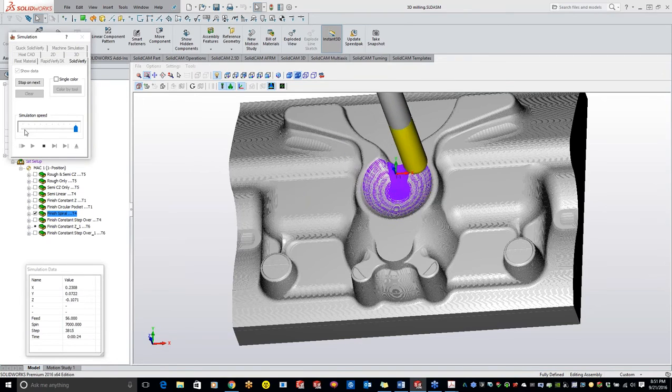And you'll notice the simulation is going a little bit slower, and that's because I'm showing you guys every single G code that's popping up. So you can see all my X, Y, Z moves that are going on right here, feed rate, my spindle RPM, what line number I'm actually on right here, and the cycle time. So that circular pocket, we're only 42 seconds in right now. So 47 seconds total cycle time.